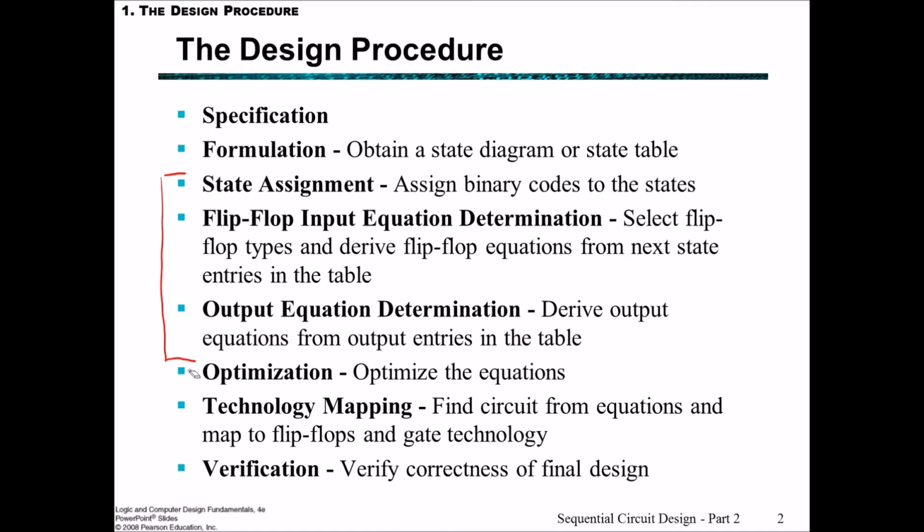And then we go back to our normal steps, which is to optimize these equations to map the technology depending upon what the specifications are. That might be we need to use NAND gates, or we may need to use NOR gates, or we have certain flip-flops available in order to implement our optimized equations. And finally, we verify that the final design that we've created is correct according to the specifications.